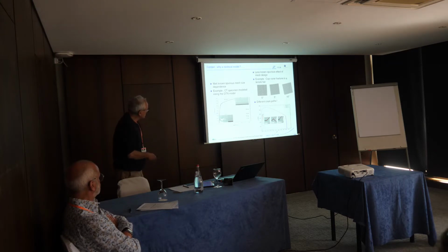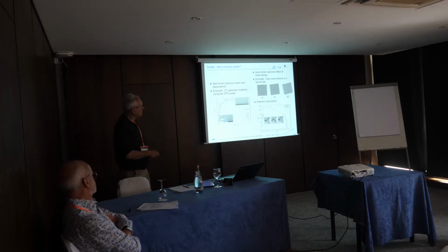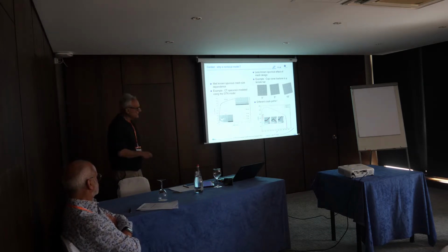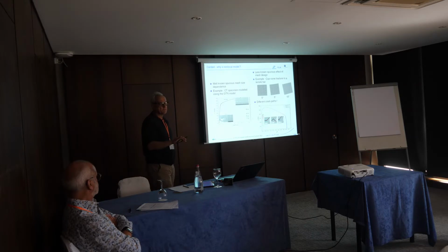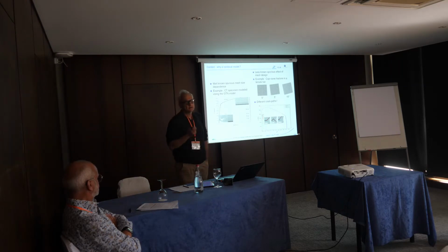What we see here is the load displacement curve is exactly the same, but if you look at the crack path, and here in red the broken elements, for 0 degrees, a standard mesh, we have what we call a cup-cone fracture: at the center of the tensile bar, a flat crack, and then it deviates to form a slant fracture. With 5 and 10 degrees, we get a completely different crack path, which means that using the standard local models, it is absolutely impossible to predict crack path.